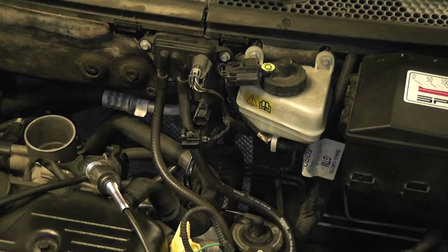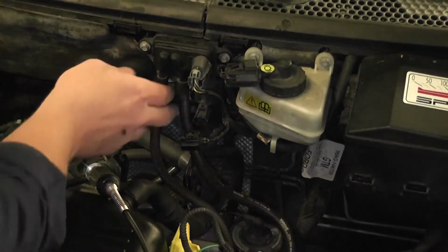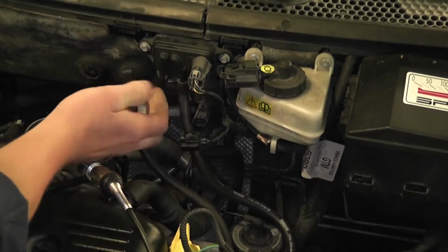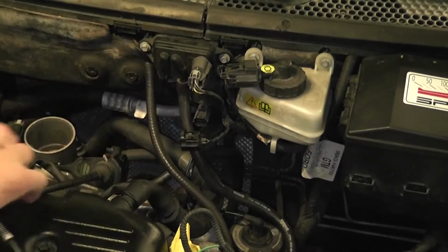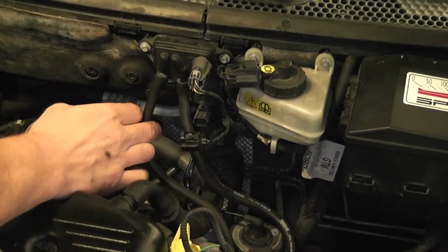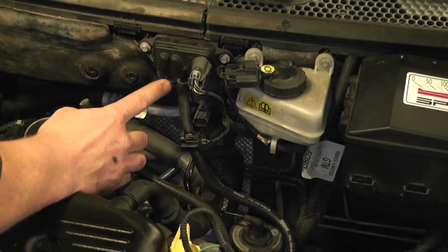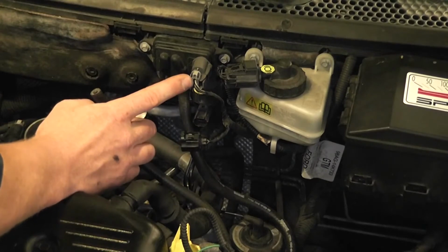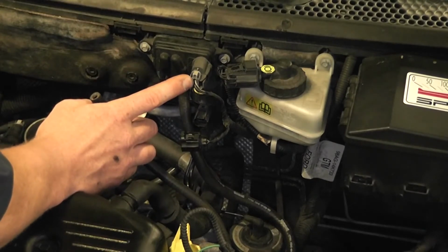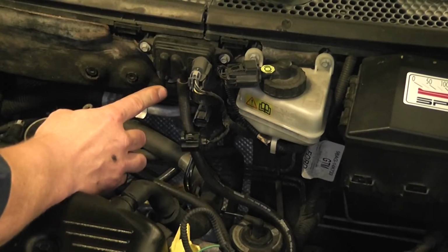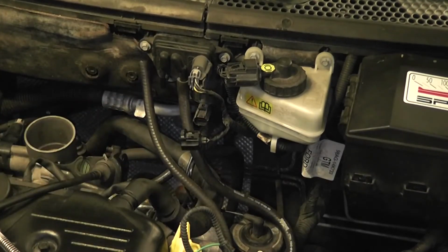In a case like this, I think one of the methods that's important to show is that you can check just the DPFE by itself, and what you would do is leave the key on and you disconnect the smaller of the two hoses on the DPFE sensor, take a hand vacuum pump to the smaller port with the key on, and you monitor your DPFE voltage, and it should increase to over 4 volts as you apply vacuum to the smaller of the two ports. So I'm going to show you that one.